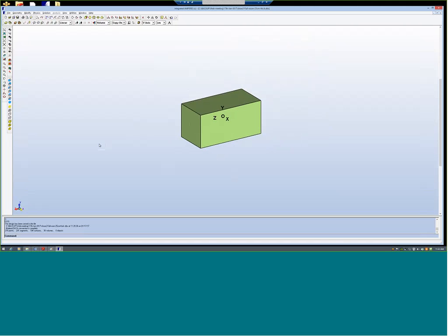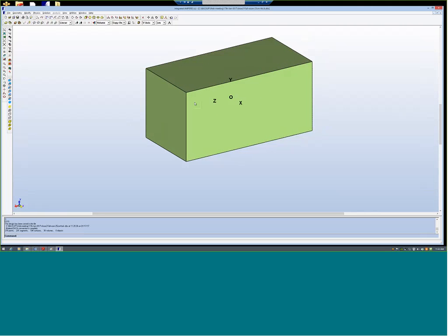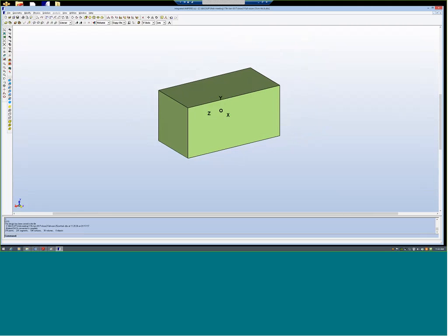You can find that out if you are using the boundary element method. If you want to use the finite element method, there will be an artificial truncation of this region, and for this kind of open region problem, the finite element method is not good. It takes too much time, and the accuracy suffers, because we are interested in the smaller values of the fields outside.